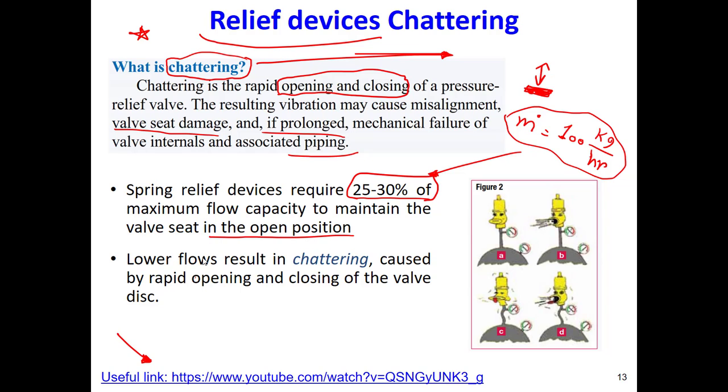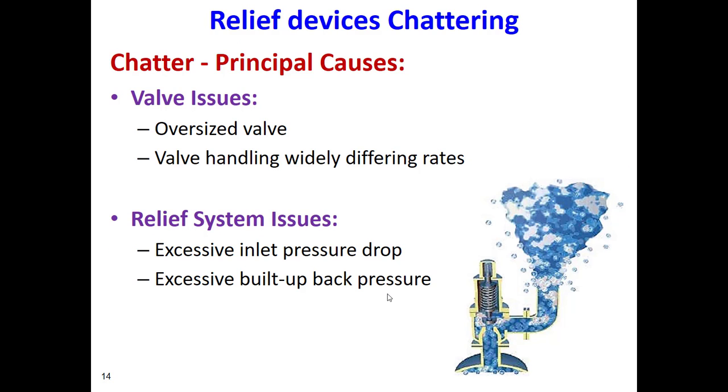Otherwise, the valve will be chattering. Lower flows or lower flow rates, lower velocity will lead to chattering. That is the issue, and it can damage the valve. You can watch this video; I think it will show it in a better way.